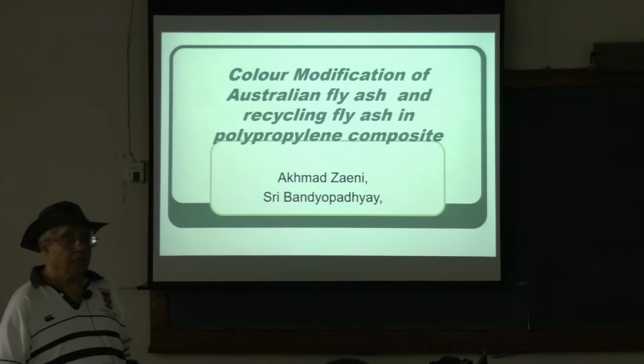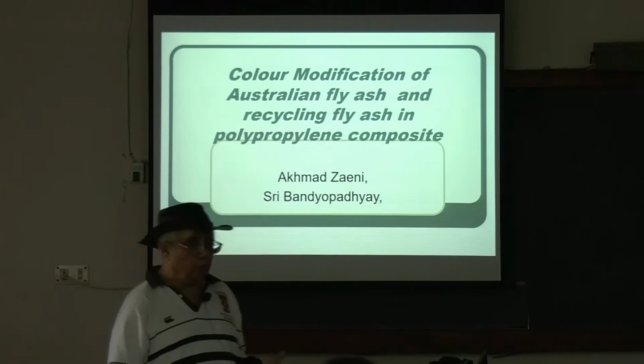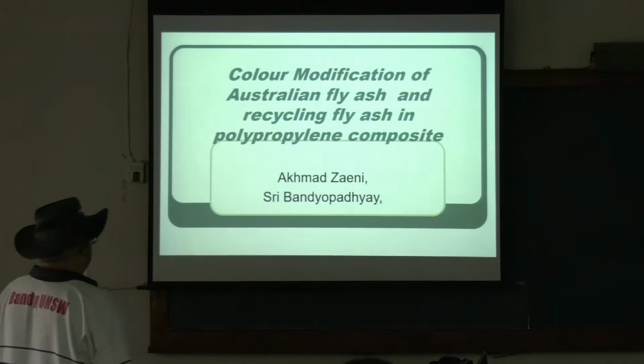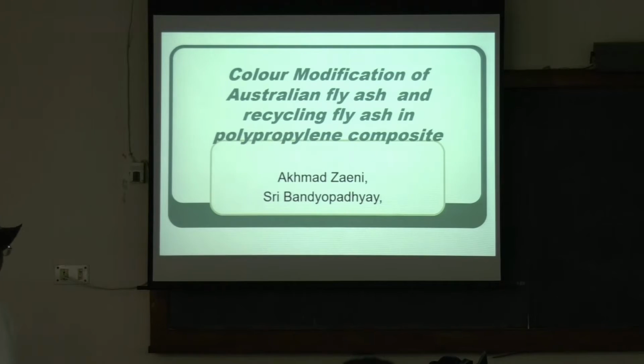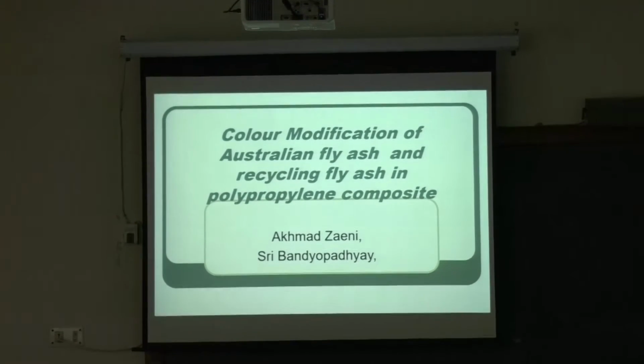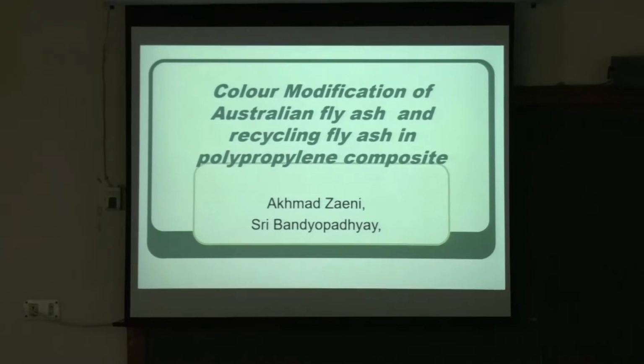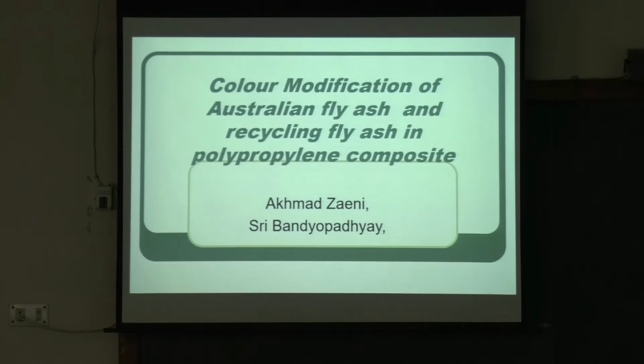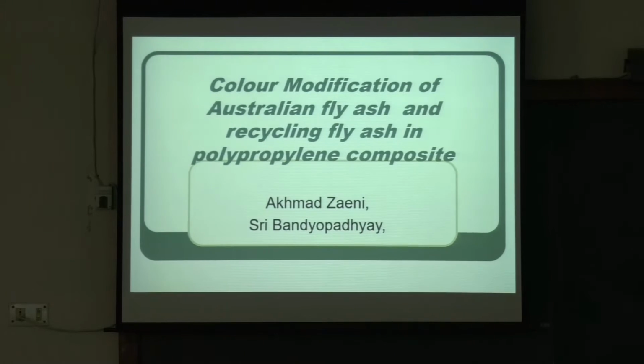I have shown you part of our work on polypropylene reinforced fly ash. And this will show some extra features. Remember in the earlier lectures where we put polypropylene fly ash, we did not mention anything about modifying the surface of the fly ash. Because if you put fly ash in polypropylene, sometimes you can get a drop in strength and other things. So that kind of thing can happen in many parts.